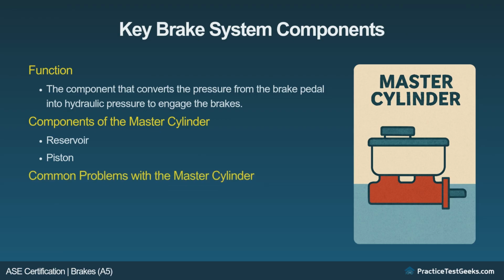Common problems with the master cylinder. Brake fluid leaks. Leaks can occur at the master cylinder seals, reducing brake fluid levels and affecting braking performance. Fading pedal feel. A loss of pressure in the master cylinder can cause the brake pedal to feel soft or spongy.